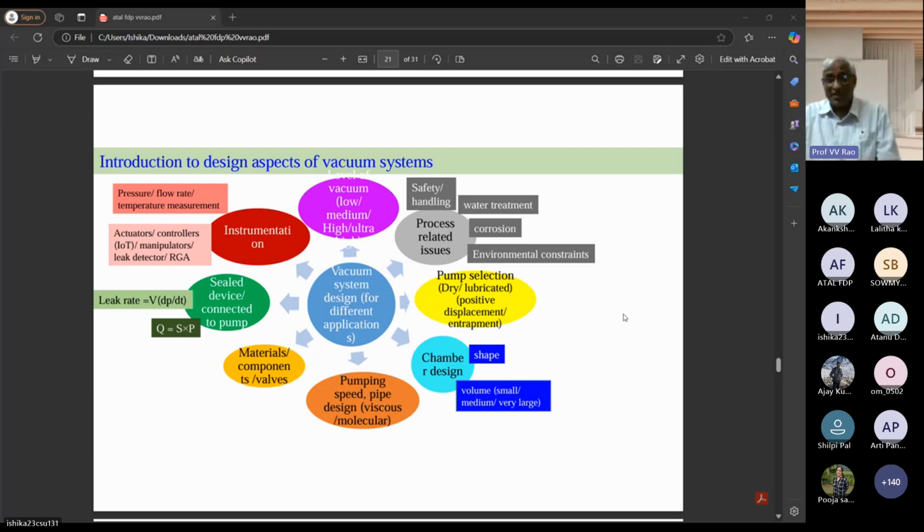Environmental constraints have to be seen. Wherever you are throwing this gas, silane gas in the semiconductor, all the way from the turbo chamber through the pipe, turbo pump, rotary pump, and in between turbo and rotary, there is another pipe that also has got conductance. And then finally it comes to the rotary and gets exhausted to the atmosphere. Not allowed. Your next fellow will say, I don't want your silane out. So how are you going to do that? There will be scrubbing actions at the end of it. You have to wash it, so exhaust management is very, very important. That is a system design concept.